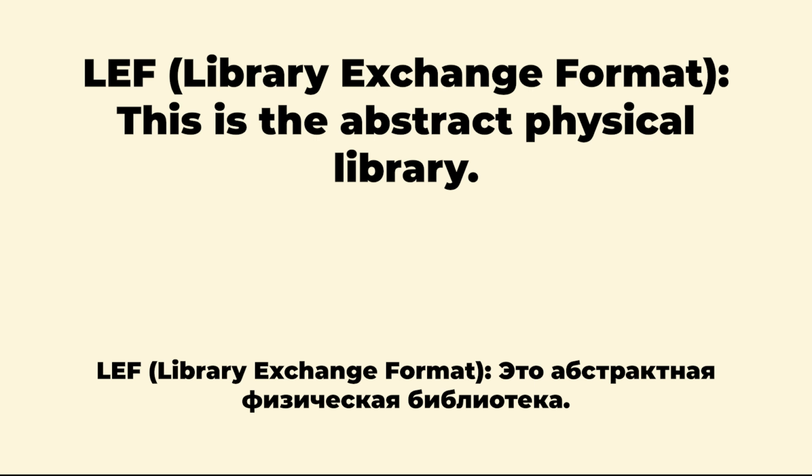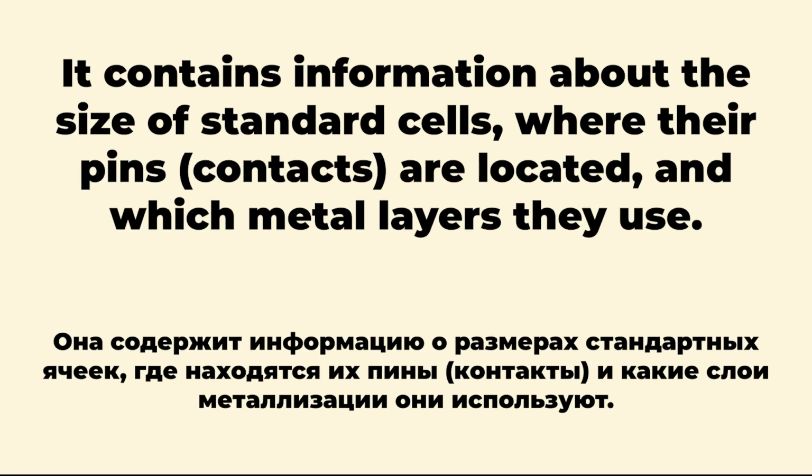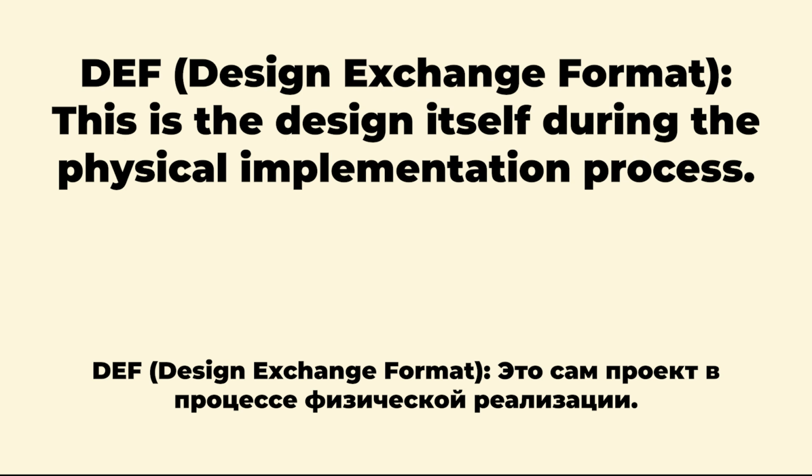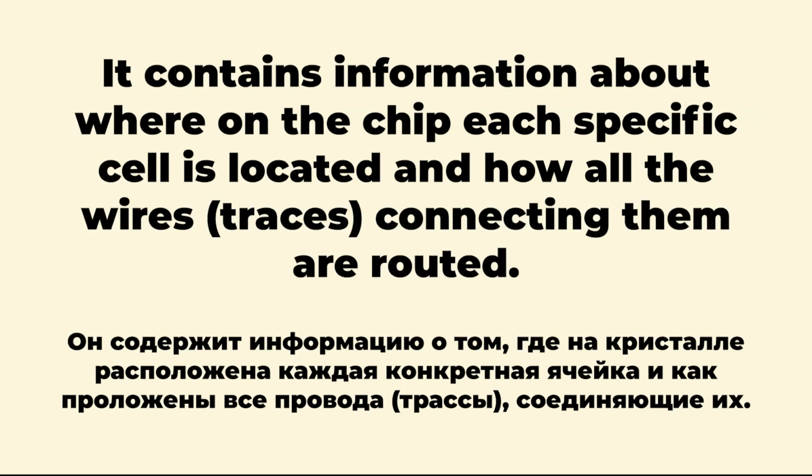LEF, library exchange format. This is the abstract physical library. It contains information about the size of standard cells, where their pins, contacts, are located, and which metal layers they use. It does not show the cell's internal schematic. DEF, design exchange format. This is the design itself during the physical implementation process. It contains information about where on the chip each specific cell is located and how all the wires, traces connecting them, are routed.